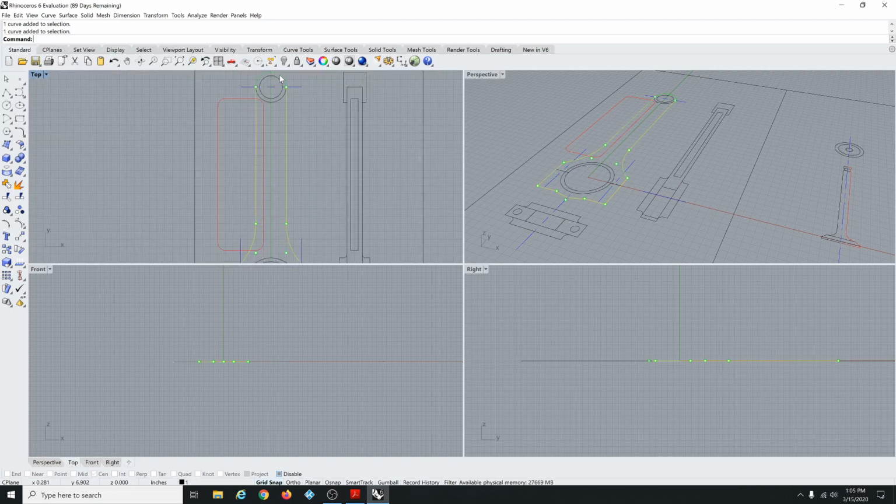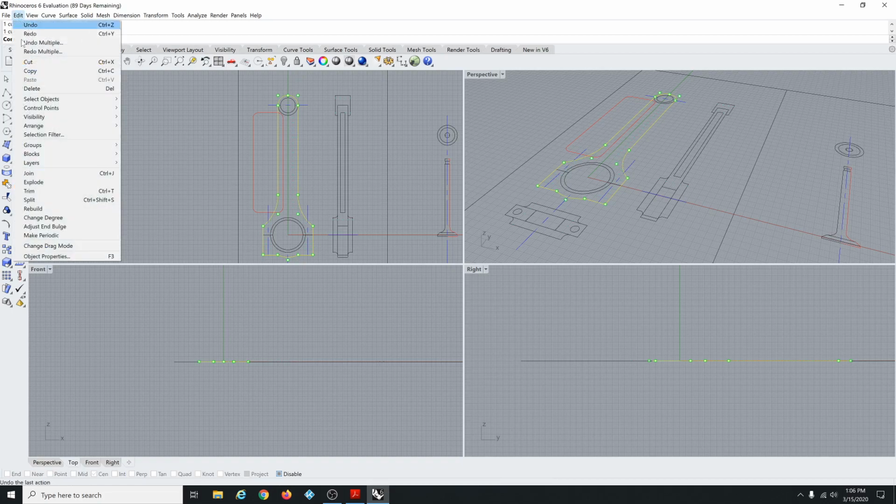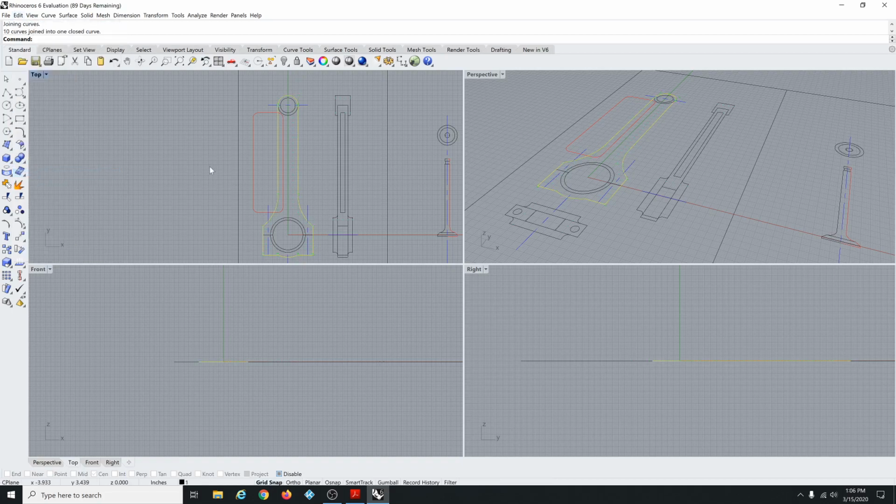And there's a green arc at the top, and it gives us the selection window here because there are 2 objects in the same spot. So we want to make sure we select the green arc. Okay, so we've got basically the perimeter of this thing selected. At this point, it's good to go Edit, Join, and you can click this again to make sure that it's all selected together. So once again, if you click, it should select everything.